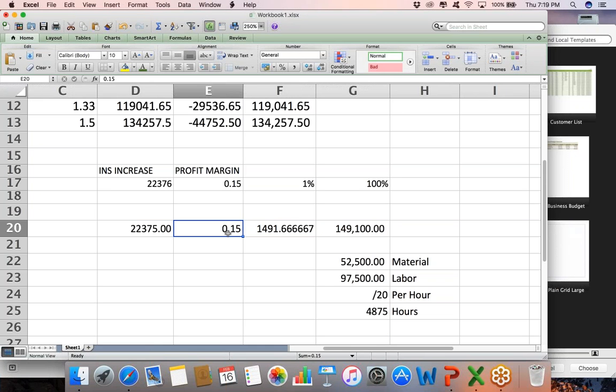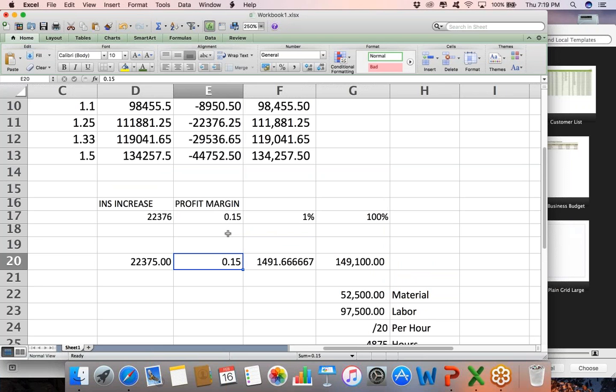And then you have the Construction Users Roundtable, right? Basically, it's reporting that's estimating the cost of maintaining an effective safety program. They're looking at it and saying it's about 2.5% of the direct labor cost. So again, let's say our labor cost was $315,000 in that one situation. 315,000 times 2.5%. Many companies, I'm telling you, are somewhere around 3%. So if we're at $315,000 on that labor cost times 0.025, we're looking at almost $8,000 per year. If you're looking at $1 million, you're looking at about $25,000 in safety cost.